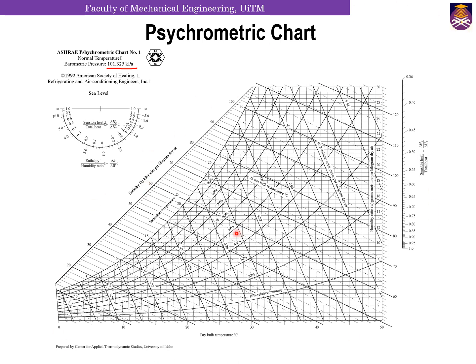These are the parameters that you can actually obtain from a psychrometric chart. And remember, again, we can only use the psychrometric chart when the pressure is 101.325. Nothing more, nothing less than this. Anything more than this or anything less than this value, you will need to use the formulas that we discussed earlier. So even 100 kilopascal, you cannot use the psychrometric chart. It has to be 101.325 kilopascal or 1 atm.